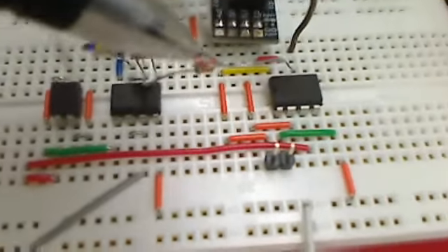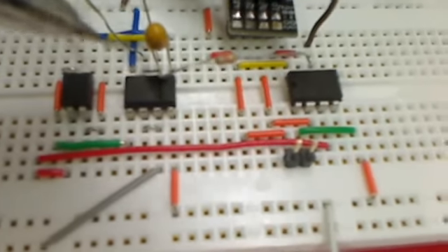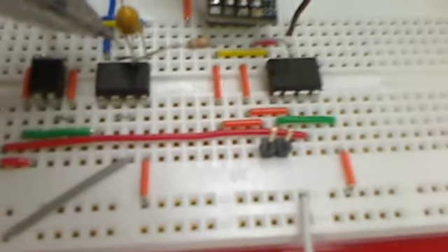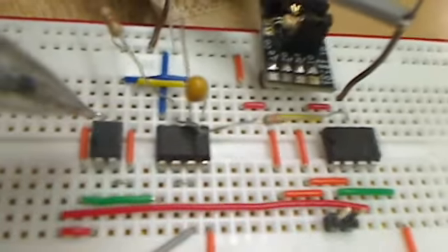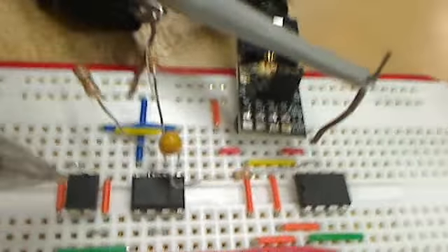Here's one part of the voltage divider, the square wave coming out of the PIC microcontroller comes up through the voltage divider. This is the other side of the voltage divider, and a reduced size square wave is then used to control the current through this resistor here, that then charges the capacitor. This is the power MOSFET that we're using as a switch to discharge the capacitor at the end of the cycle to start a new integration.